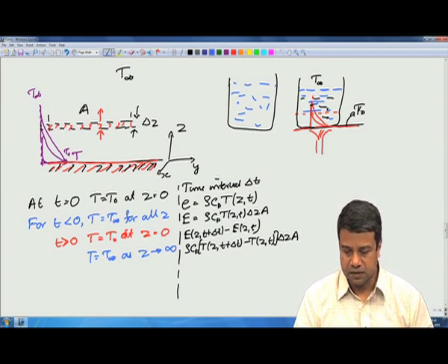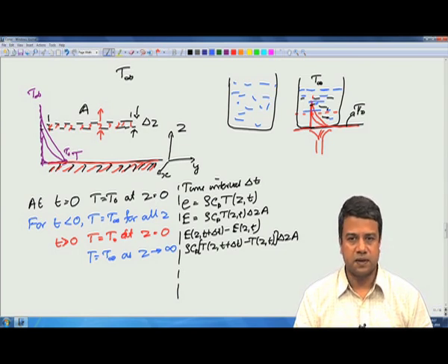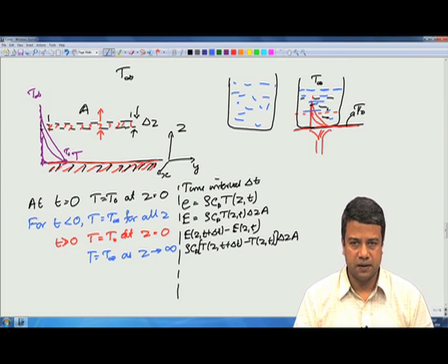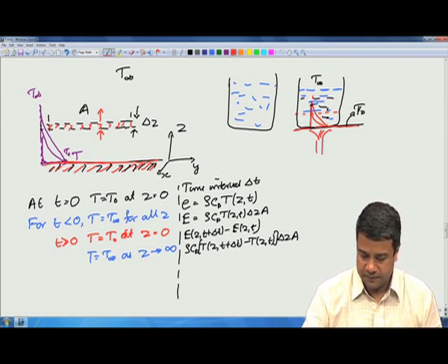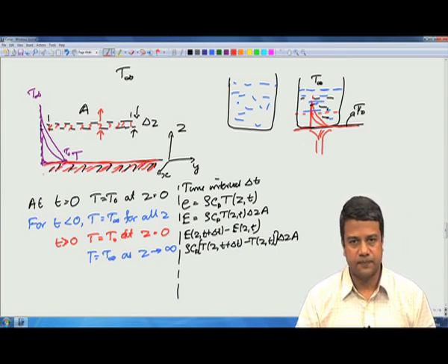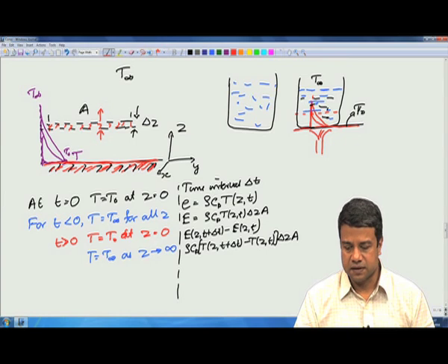Okay. So, for definiteness, what we had was a surface at z is equal to 0. So, we use a coordinate system where the x and y directions are along the plane and z is perpendicular to the plane. So, we had the surface with initially the temperature a constant everywhere in the fluid, and instantaneously at time t is equal to 0, this surface alone was heated to a higher temperature. The surface alone was heated to a higher temperature, and we wanted to know how this increase in temperature at the surface is going to heat up the fluid. Note that in this case there is no convection, therefore, there is no fluid flow perpendicular to the surface, therefore, transport has to be due to diffusion alone.